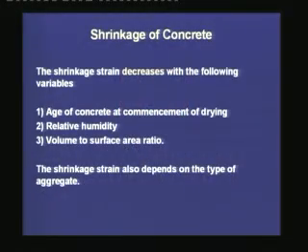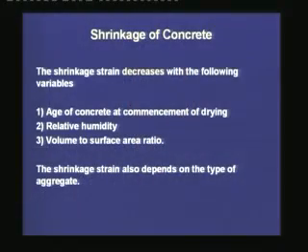Age of concrete at commencement of drying. That means if we cure the concrete for a longer period, and then if we apply the pre-stress or put it into service, then shrinkage is low. Next is relative humidity. If the relative humidity goes up, then hydration is better, loss of moisture is less, and shrinkage will be also less.